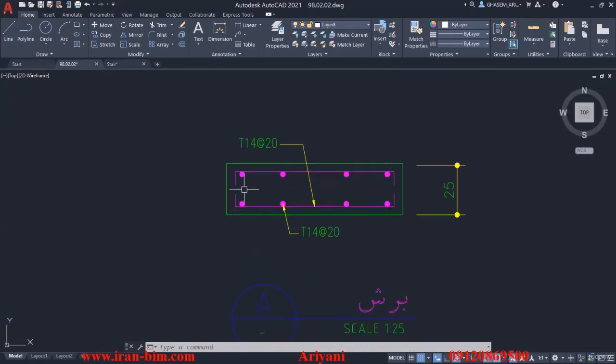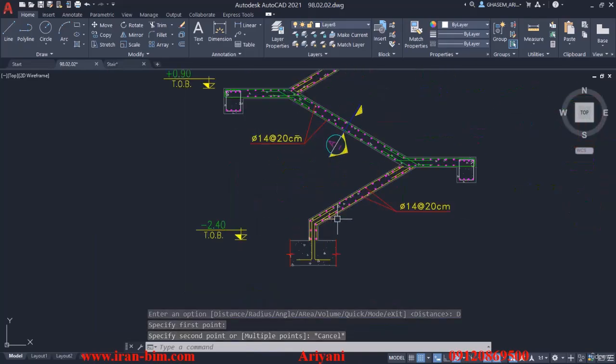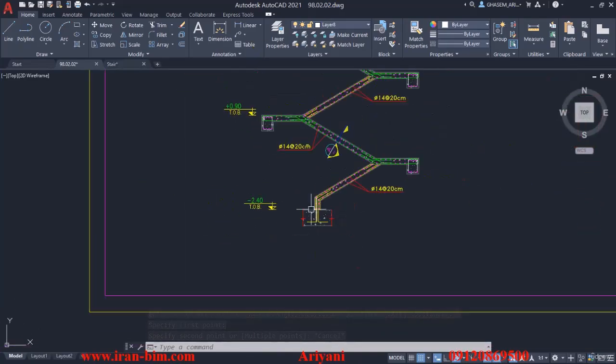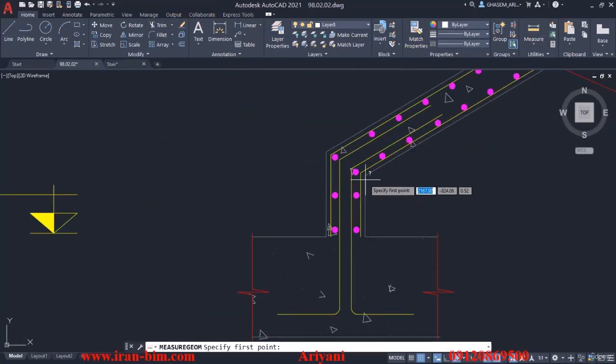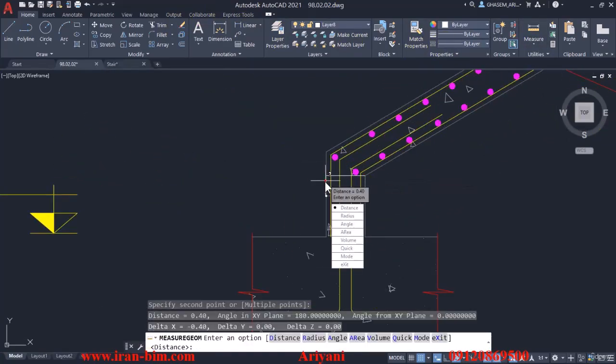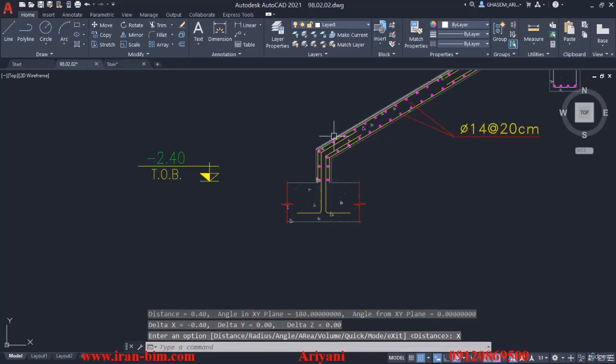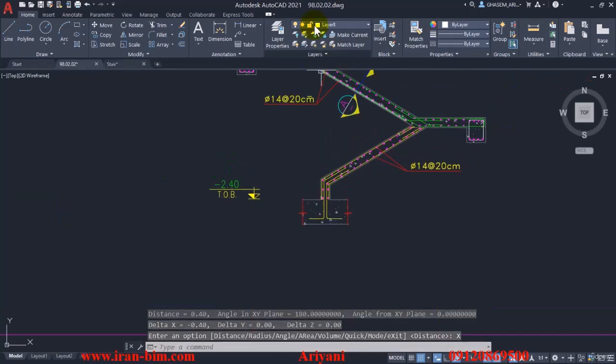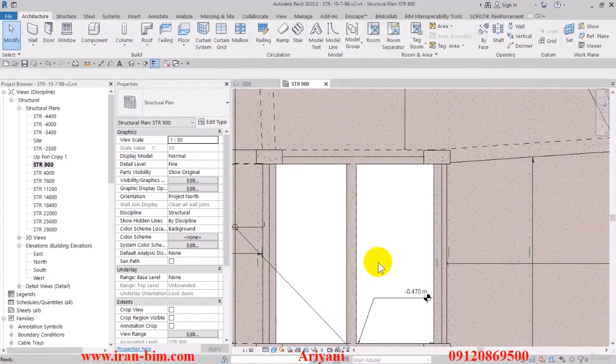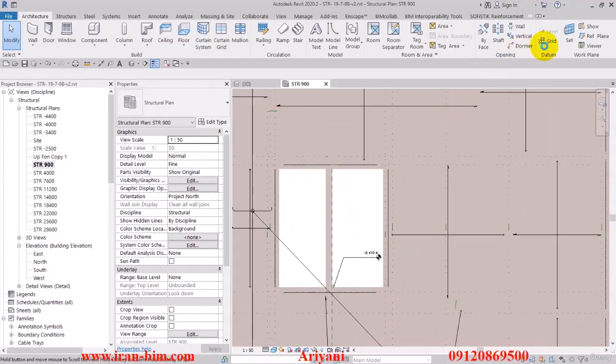It's right here, and this cut explains to us how the formation of the rebars is going to be. So I'll go to the cut itself and then use the distance and measure tool to check the distance here. It says 0.4, and this has been modeled to a scale of twice the normal size, so whatever number we get here, we have to divide it by 2.